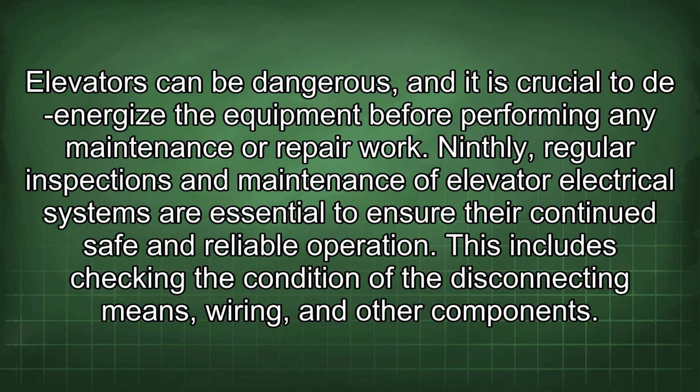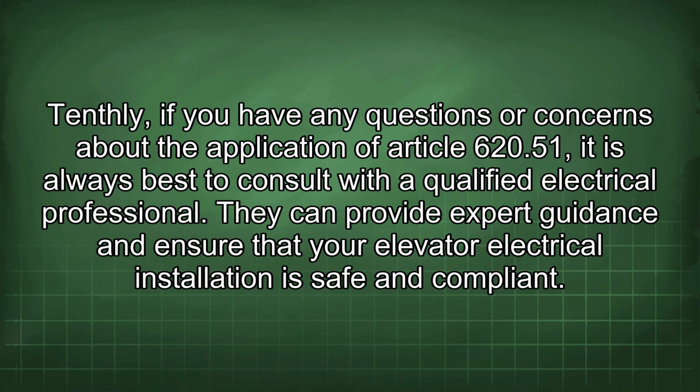This includes checking the condition of the disconnecting means, wiring, and other components. Tenthly, if you have any questions or concerns about the application of Article 620.51, it is always best to consult with a qualified electrical professional. They can provide expert guidance and ensure that your elevator electrical installation is safe and compliant.